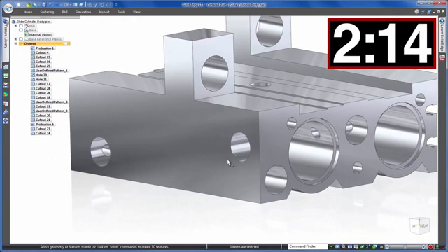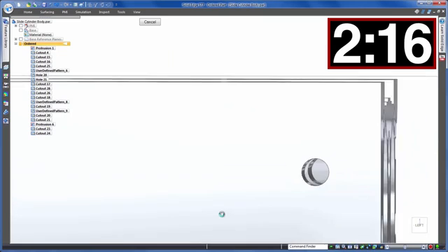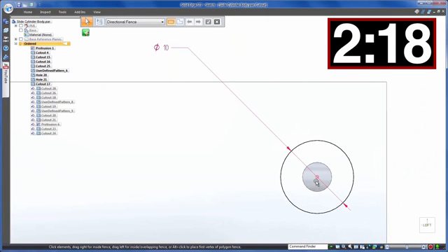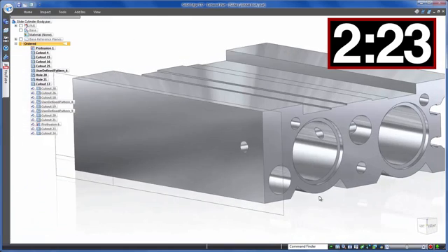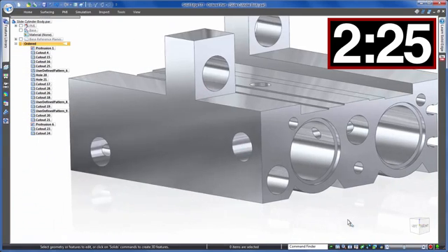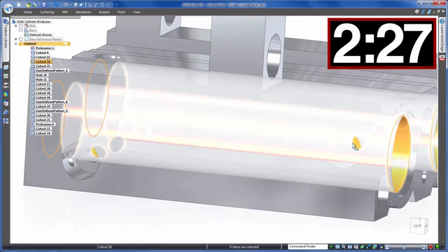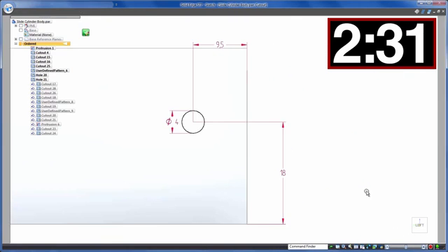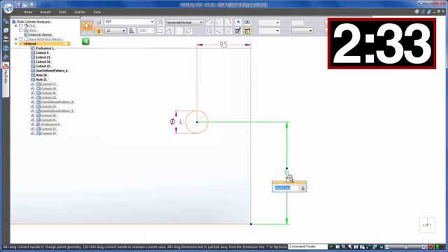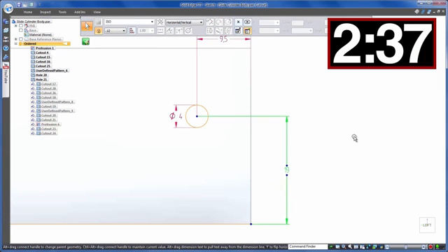We need to do the same with the top counterbore to total our required 2mm clearance, but repeating the same steps, notice that this wasn't created in the same way as the previous. Instead, it has two cuts, one concentric to the other. These sorts of frustrating situations are often run into in history-based modelling. Design intent may not be what you'd naturally expect. It's all down to the original decision and creation. Another fix required.